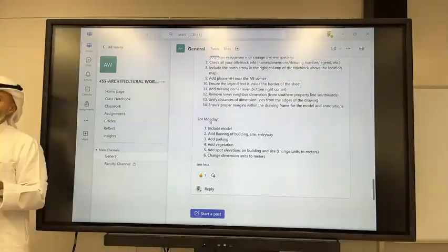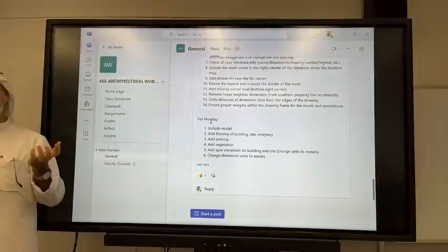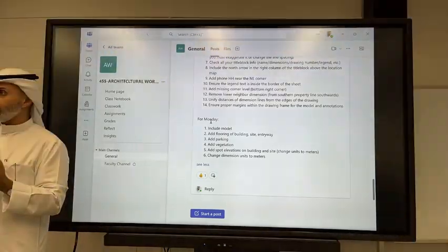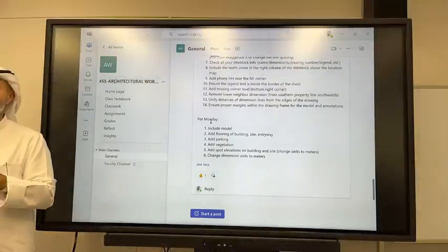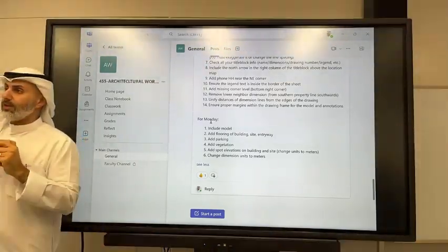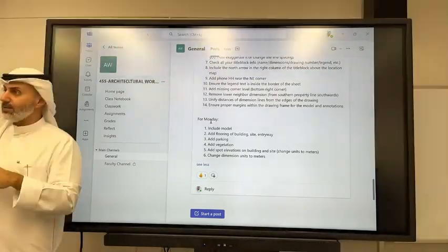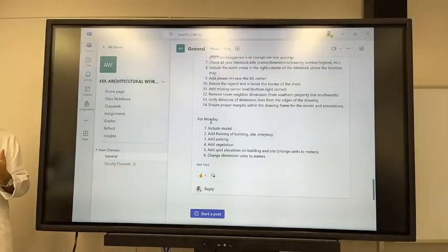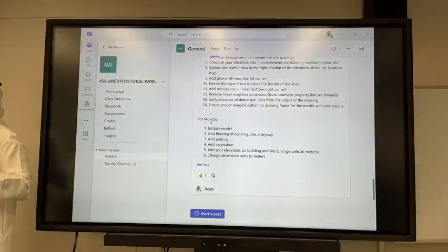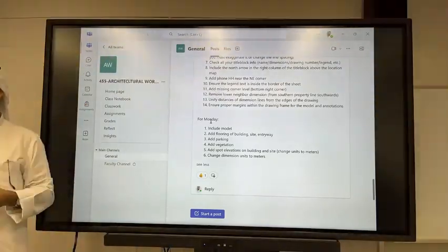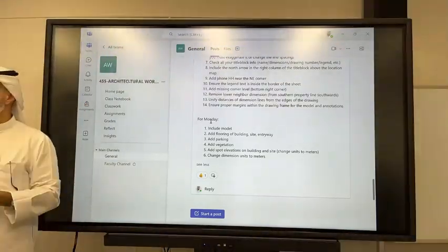Now, last week what we did was change the project units to meters. Right? Now, to make our project easier, so we don't go into that, what are our project units now? They're not meters, right? They're millimeters. It's my site, so it's going to follow my project units. So it's going to show 25,000 millimeters as the plot width. So we're going to customize the dimension style to show meters. I'll show you how to do that now.